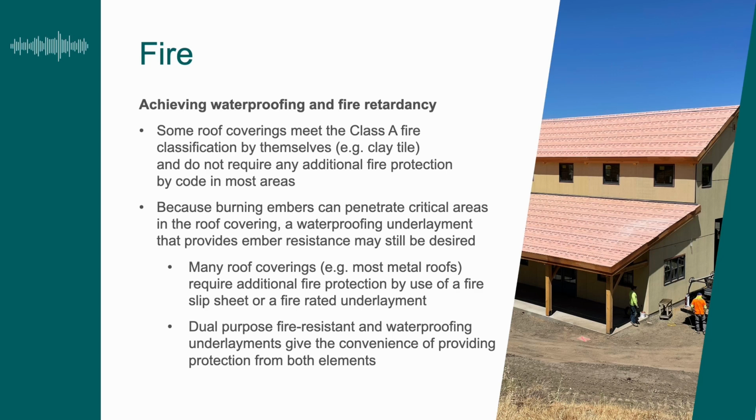Specialty underlayments can be put with various roof coverings, and those can often be used in exchange to increase the rating on any assembly that most manufacturers have. Class A is the most severe: a 6-foot spread of flame, and then penetration and burning brand, which are done for combustible decks.